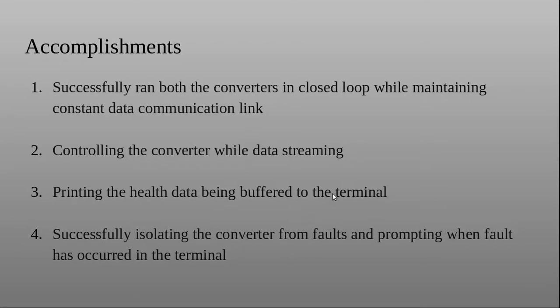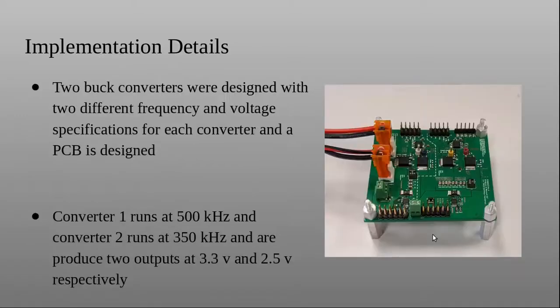And also we are printing out the temperature of the MOSFETs and the voltages that the converters are controlling. Now we were also able to successfully isolate the converter from faults, and the fault would be prompted immediately on the terminal so that the user can discern what kind of a fault it is and act accordingly.